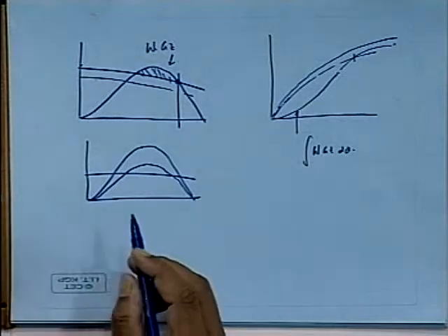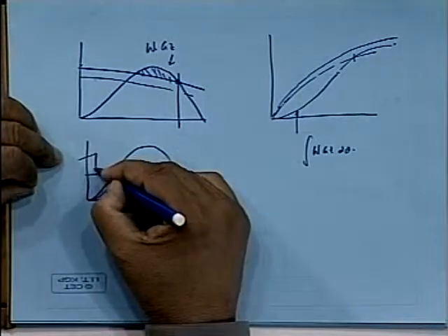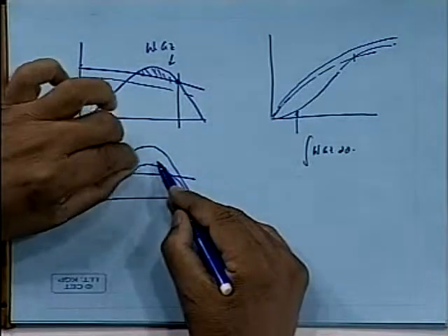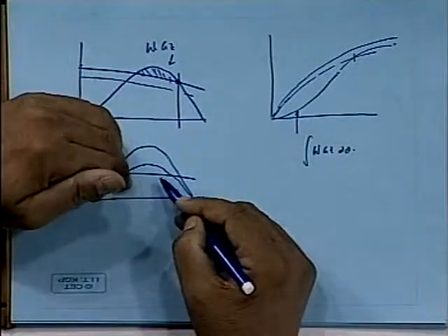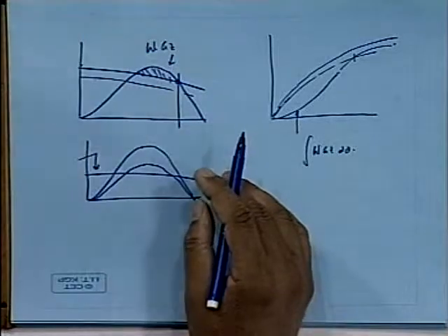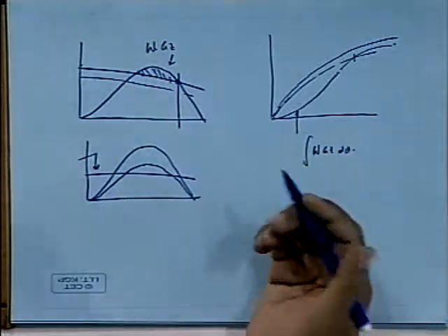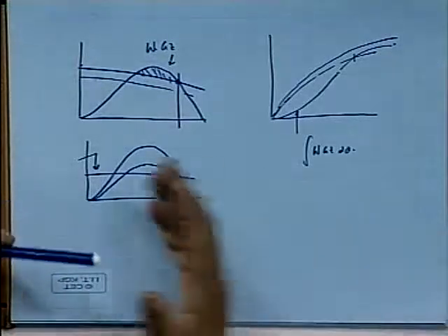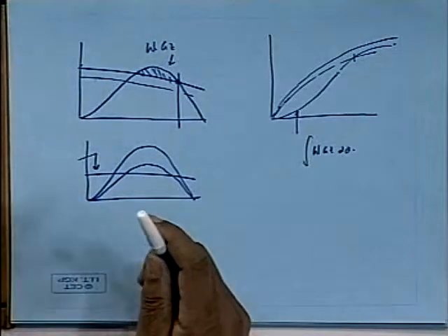Therefore, what is necessary is that for a given wind heeling moment, you must have enough area under the GZ curve, or for a given GZ curve, it can only withstand a certain amount of wind heeling moment. Obviously, no ship can be designed to withstand all environments. Any building you design will be for a certain wind. You cannot say there is a 1,000 knot wind and it will survive. That of course is a design condition. We will catch up on that in the next lecture. This one will end here.